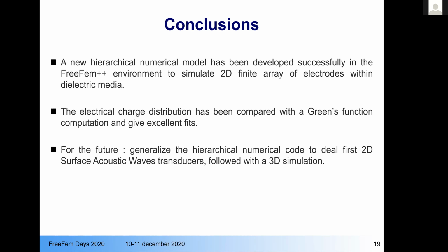Okay, Pascal, I just have some remarks. The way to do the same with general things, with piezoelectric stuff, I think it is not really difficult because the structure of the code does not change. For the 3D problem, it's another story because now the left part and the right part, which are the places where you have the degrees of freedom, have full matrices depending on this side. So if you want to play with full matrices, more than, I would say, 6,000 degrees of freedom will be a real limit. So you have to divide by 2. So you must have less than 3,000 degrees of freedom on each left part and right part.